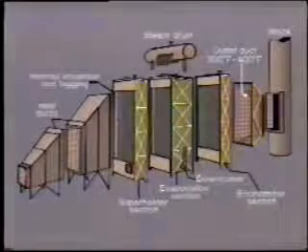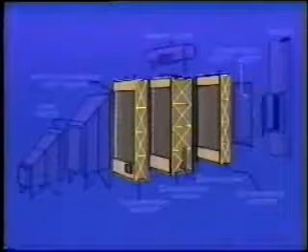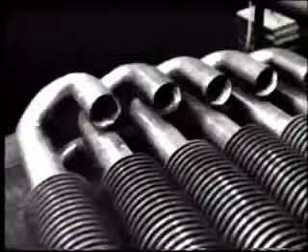The tube banks which provide the boiler heat transfer surface are installed in a modular form. For example, the economizer section is shop-built and shipped to the site in one unit like this. It is then connected to the appropriate feed piping on one side and the steam drum on the other. And here is the modular evaporator section where steam generation takes place.